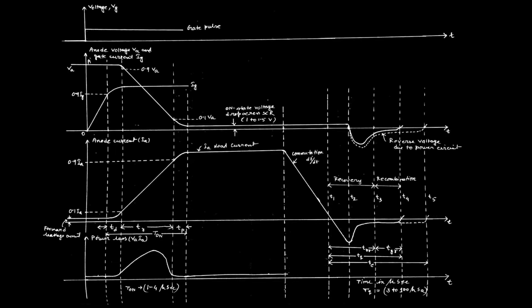It is known that the direction of current is the same as the direction of holes and opposite to the direction of electrons. In the PNPN layers, while the holes and electrons are still moving, current is internally flowing. That is why, even when we decrease the anode current to a value of, say, 0, the device is still in the working state.